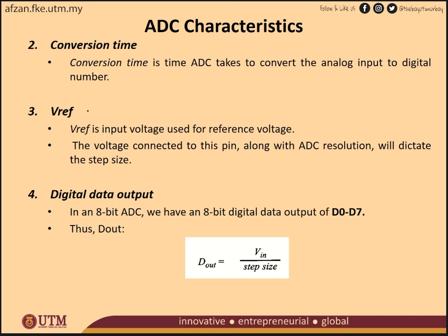And then the third characteristic that you need to know is the VREF. VREF is an input voltage used for the reference voltage. The voltage connected to this pin along with the ADC resolution will dictate the step size. Again, step size equals VREF divided by 2 power of n, the number of steps.